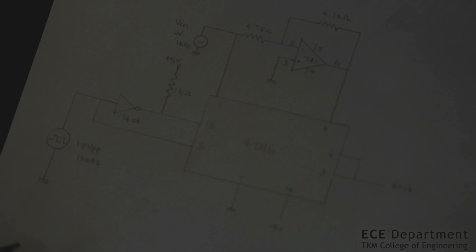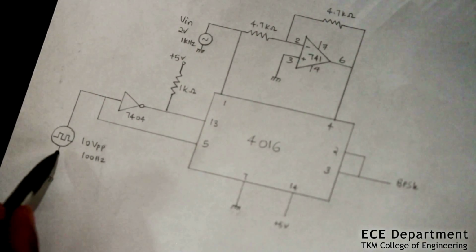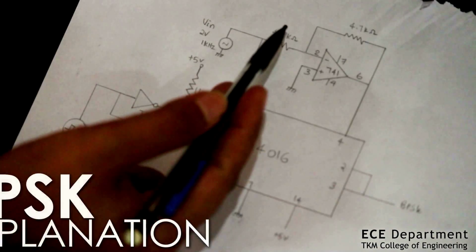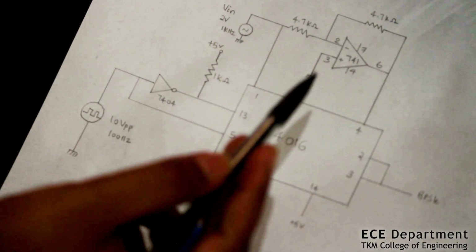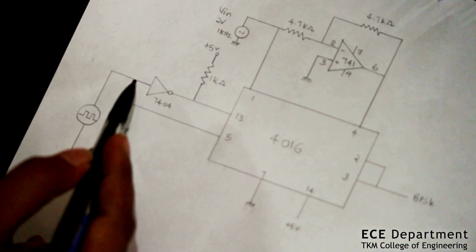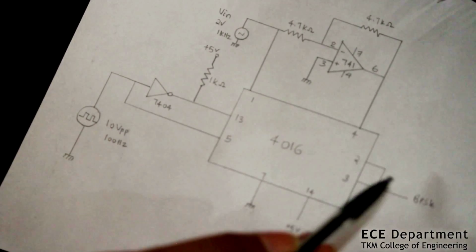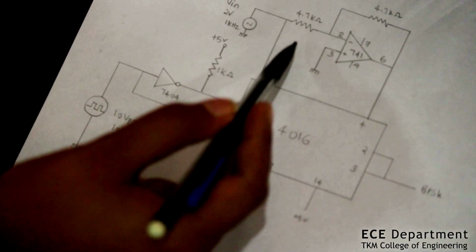Here we can see the basic circuit diagram of a BPSK, binary phase shift keying. Here we can see that the clock signal is given to the 7404, which is the NOT gate. The input signal is given to the 741, which is the operational amplifier, here which it acts as the inverting amplifier. When the clock signal is 1, we can see that the phase shifted signal comes at the output, and when the clock signal is 0, the non-phase shifted signal comes at the output.